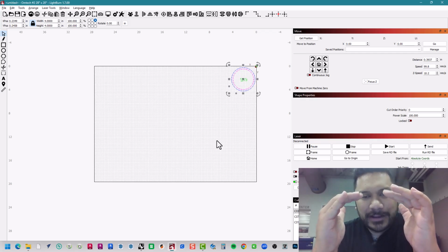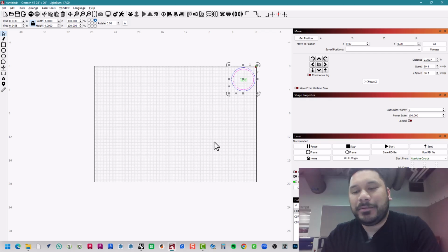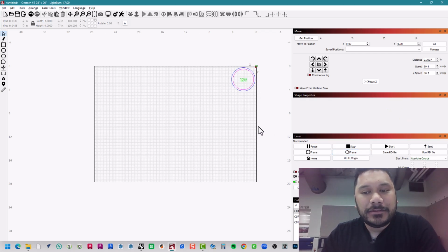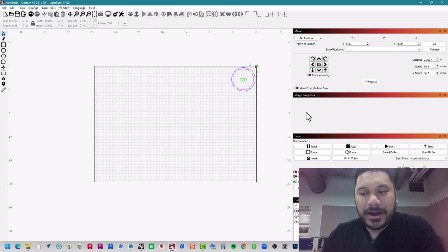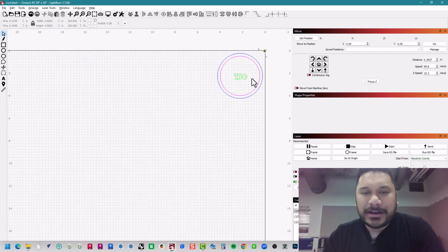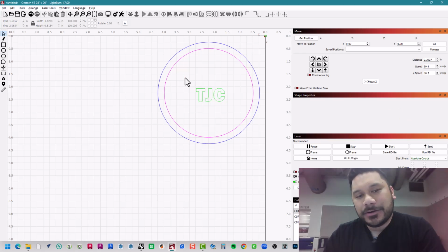And you always have to watch your projects. I mean, you don't have to look at it that whole entire time. In fact, I highly recommend you not look at the pretty laser, but you need to be somewhere nearby your job. You cannot just start this job and walk away. You could totally burn down that machine, cause a fire, and you definitely need to be nearby it just in case something happens. It's happened to me. No matter how confident you are with this thing, I would not walk away from the laser cutter while it's running. And if you do, and I see it, I'm just going to turn it right off.